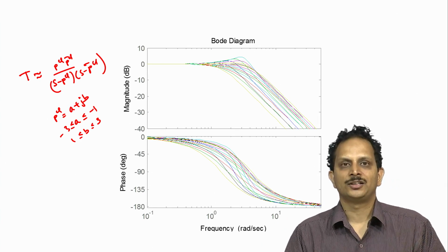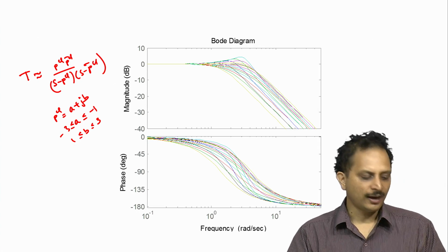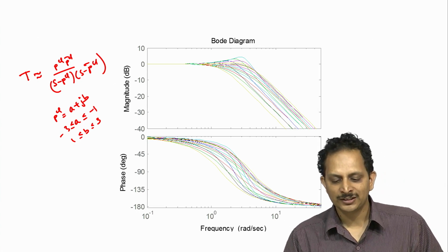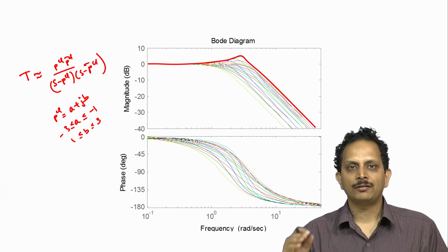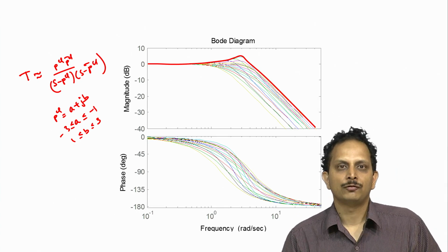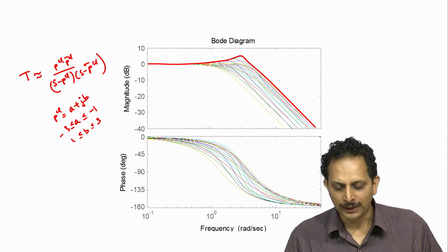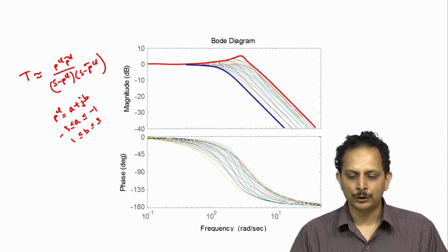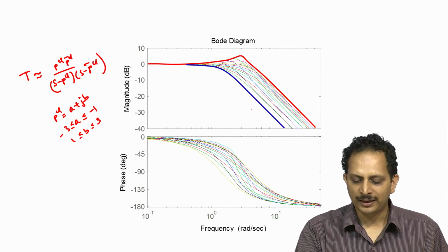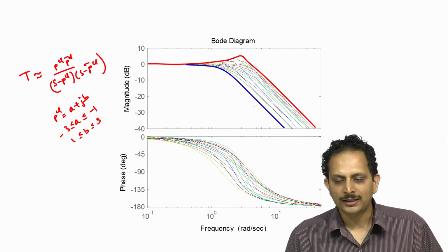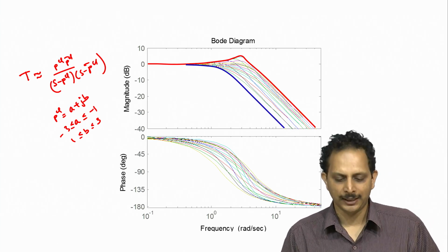Now if we look at this transmission function, what we can identify is that there is an upper limit that we are willing to permit for the variation in the transmission function, and there is also a lower limit which we are willing to permit. The lower limit has been indicated by the blue curve and the upper limit has been indicated by the red curve.